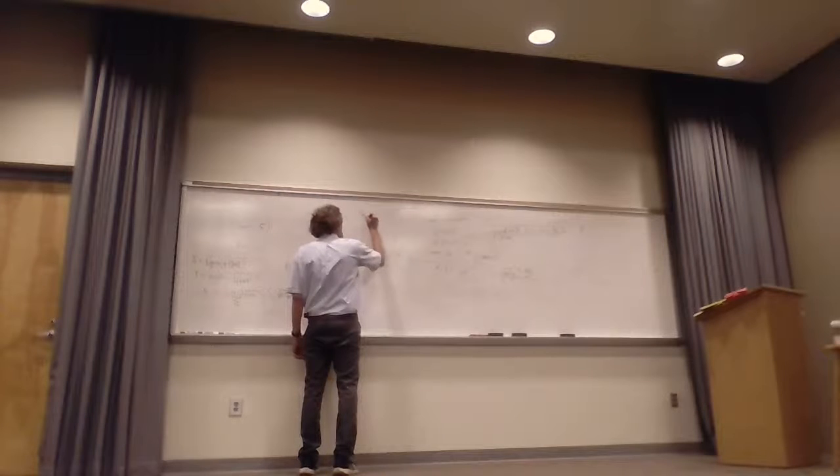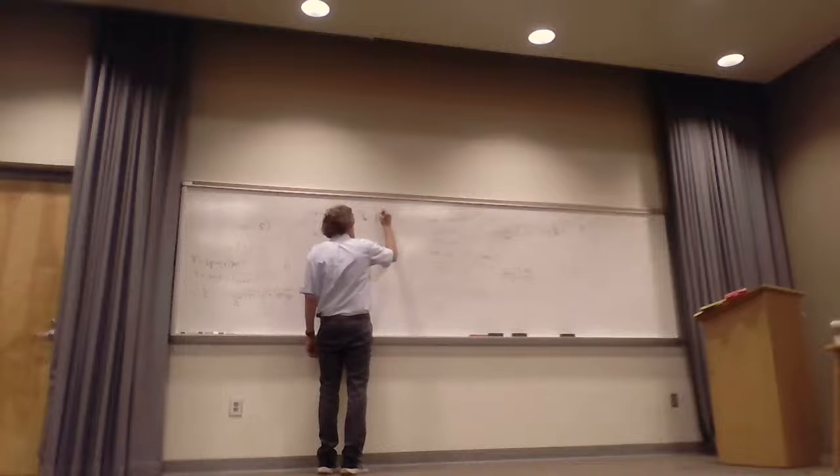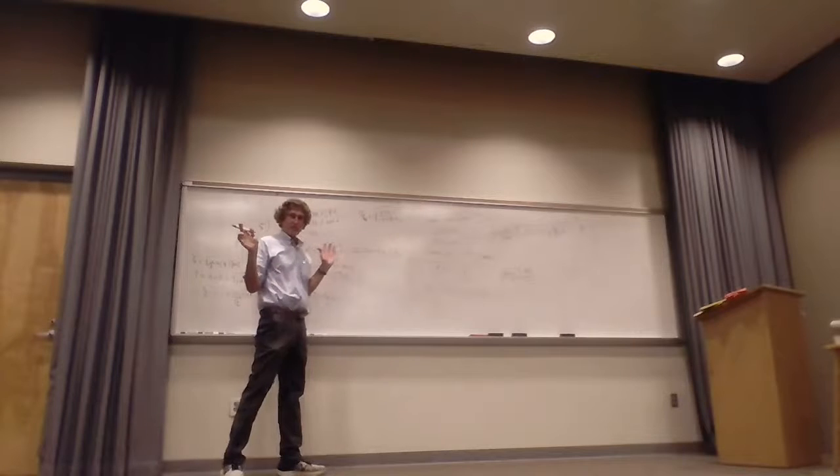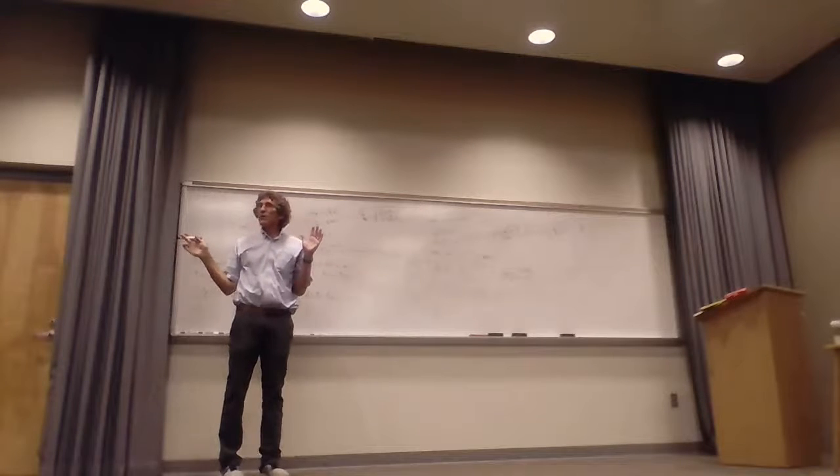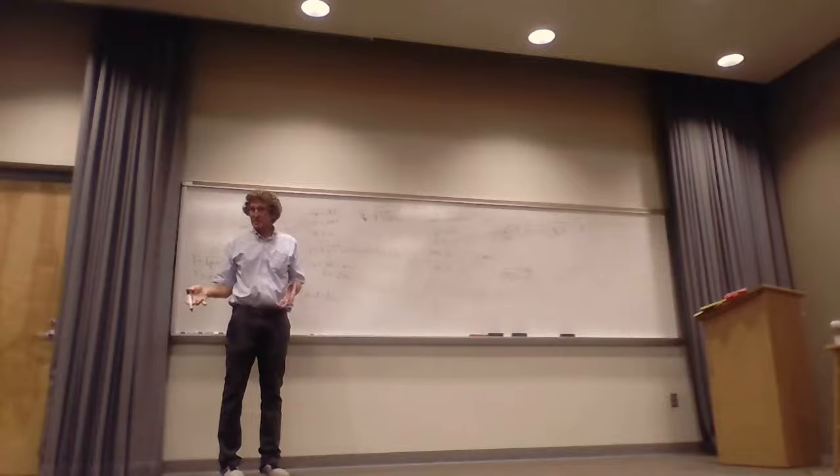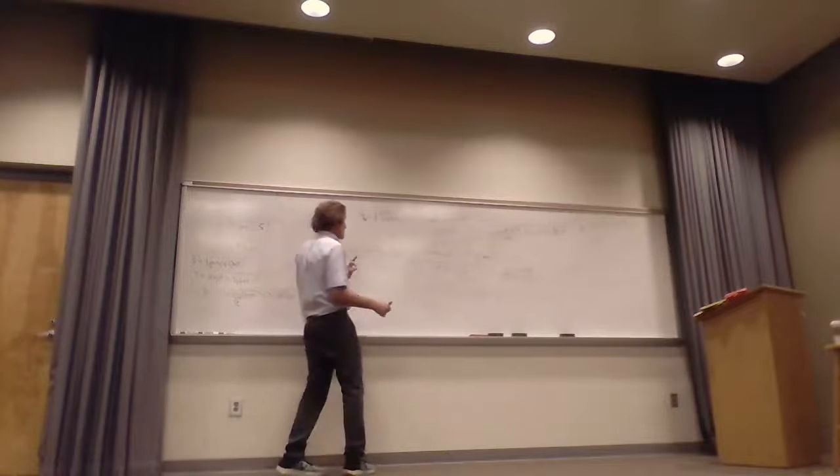Eta, the intrinsic impedance, in general is equal to the square root of j omega mu over sigma plus j omega epsilon. That's the general form for anything, right? Now, if we are in free space or the atmosphere, we can assume that sigma is about 0. I told you it's about 10 to the minus 14, 10 to the minus 15. It's about gone.